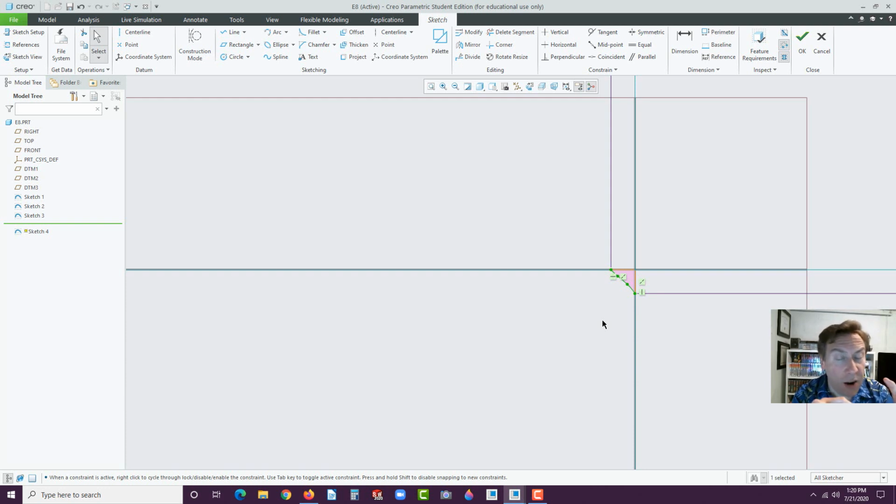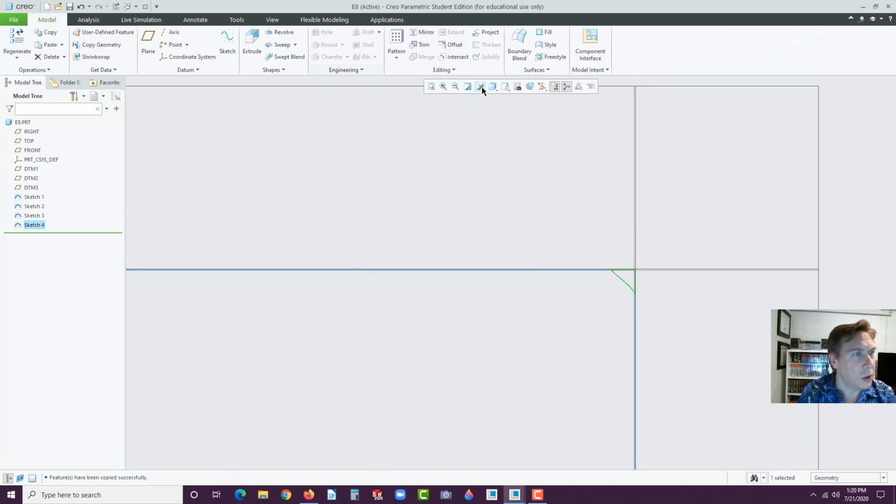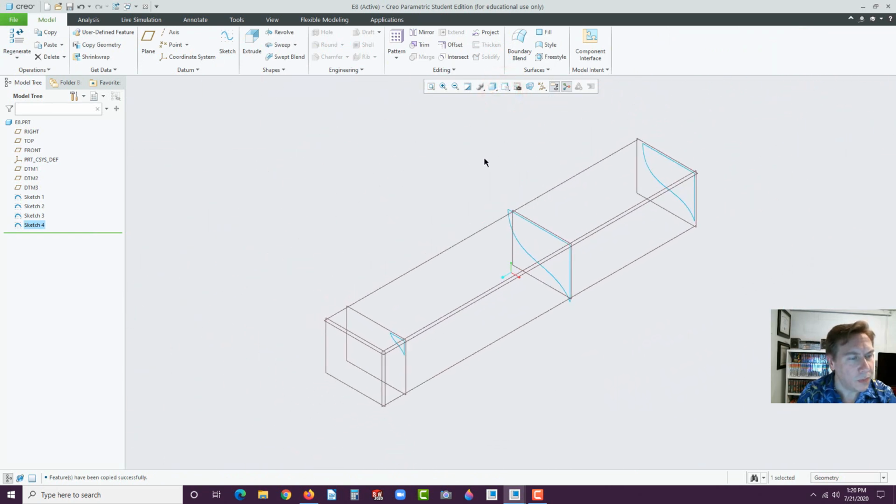Also note, if you ever are doing analytical geometry or even sketch splines, if there's multiple segments, keep the segments equal for each lofted section. So just be aware, if there are 3 segments, make sure it's 3 segments for every profile. All right, hit OK. And now let's go back to standard orientation.